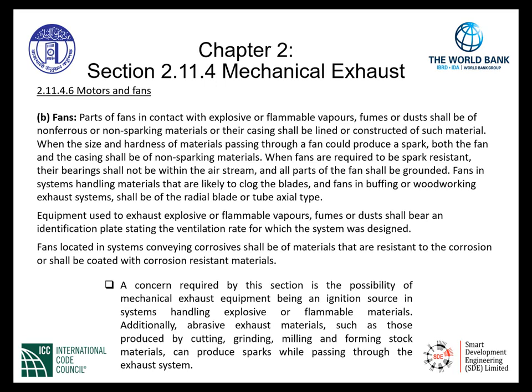When the size and hardness of materials passing through a fan could produce a spark, both the fan and the casing shall be of non-sparking materials. This is important because we are conveying explosive or flammable vapors, perhaps, given an application of a particular exhaust system. We do not want an ignition source.